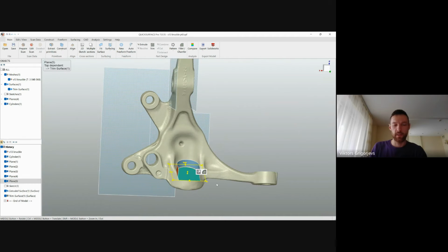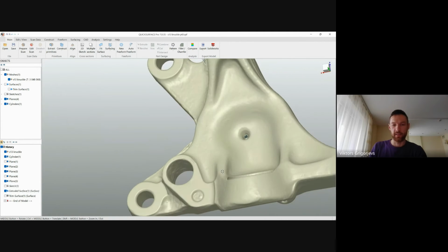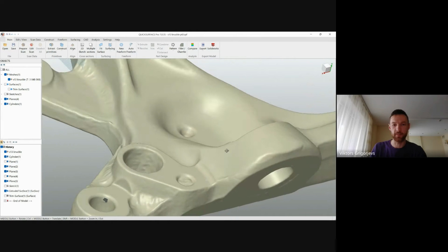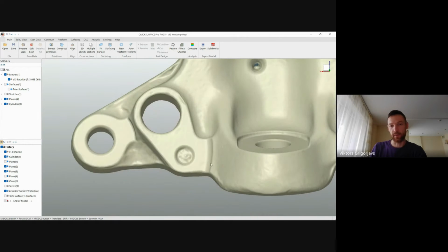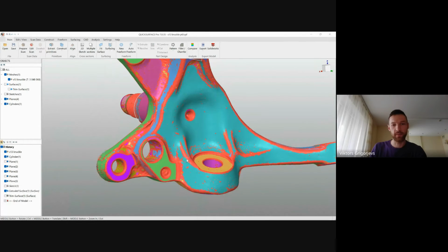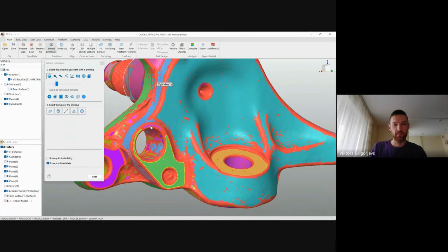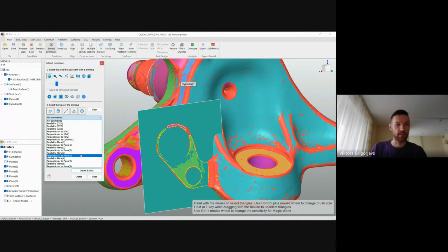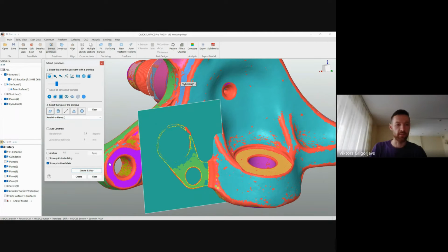Another part, which is even more interesting and requires a bit more actions, is this face. It's almost flat. Also, we need some vertical surface here from this flat position, but it's kind of curved, so we have to invest a bit more time to recreate this. Basically, again, setting a plane, making it parallel to the very first plane.